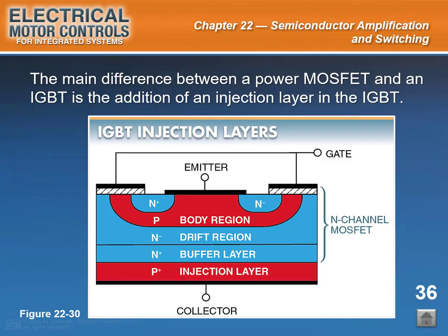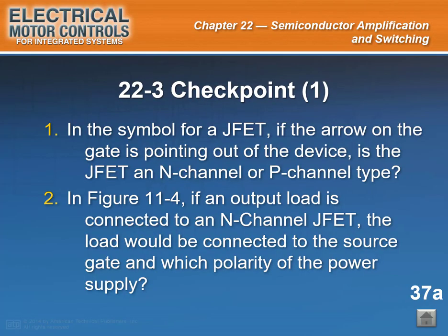This increase in conductivity of the N layer allows the reduction of the on-state voltage of the IGBT, which overcomes many issues that would not be available without this extraordinary technology. High-power MOSFETs and IGBTs are a couple of my favorite electronic devices for powerful robotic controllers. End of slide 36. Start of slide 37.